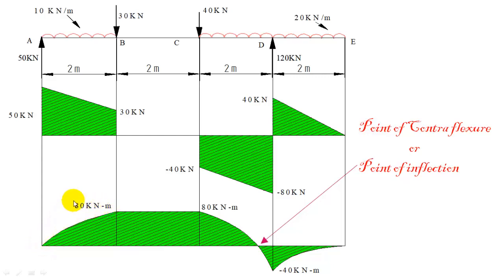And we should not increase beyond this point. If you draw a horizontal line, all the part of this curve will be below that line. Then for this section, the bending moment is constant. At C also we got bending moment as 80. B is 80, C is 80.